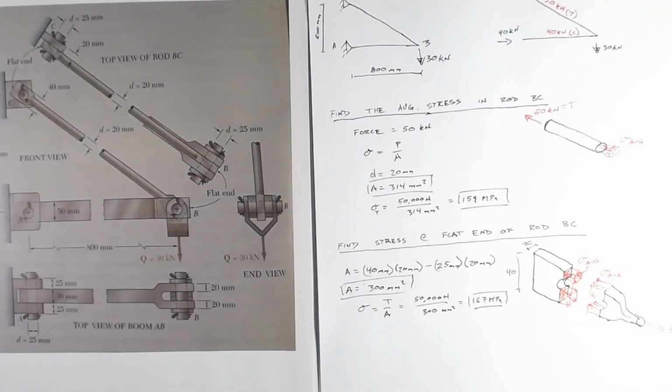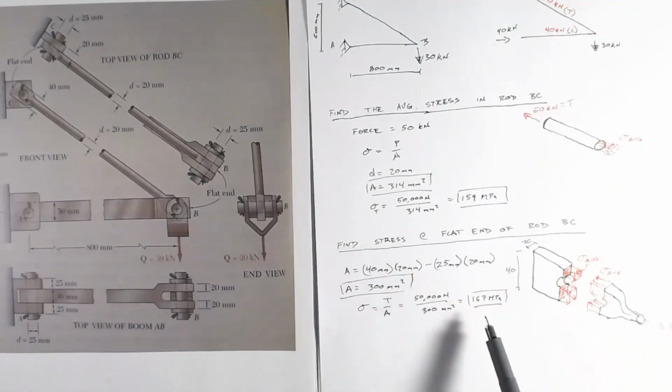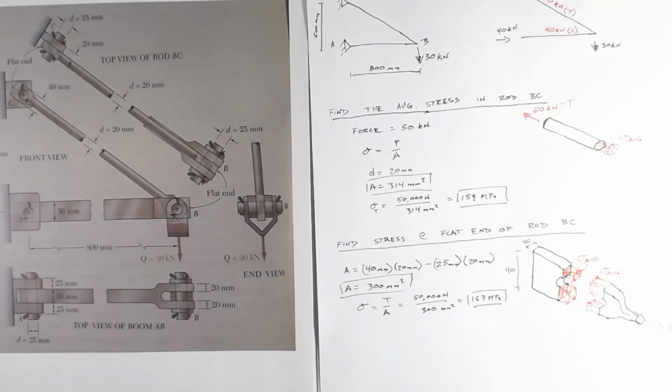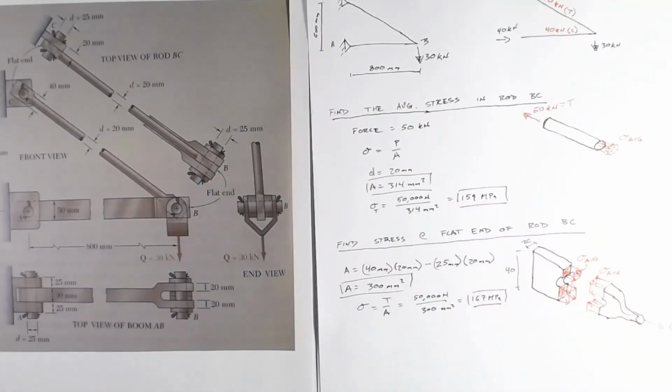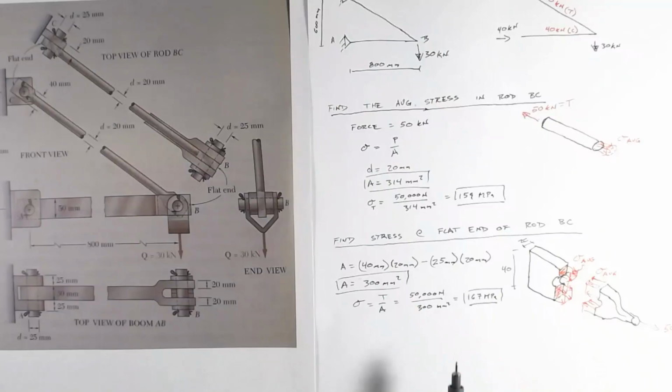We can compare that to what our stress is over the middle of the bar. Obviously, it's a little bit higher, but it's not much, and that's one of the reasons why at the ends you might need to thicken up any connection pieces when you do a design, because the whole idea is trying to keep that stress down below where it's going to be breaking.